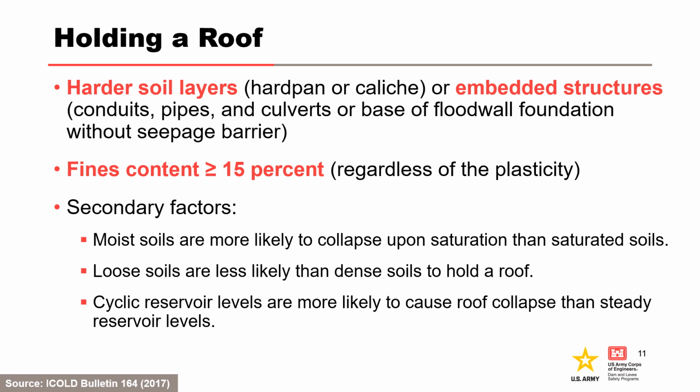Partially saturated and high fines content non-plastic soils may hold a roof near the phreatic surface, but the roof is sustained by pore pressure suction and may collapse upon saturation.